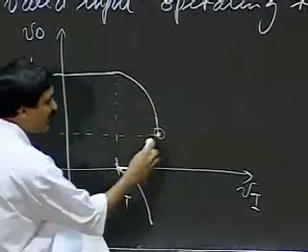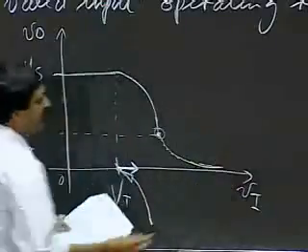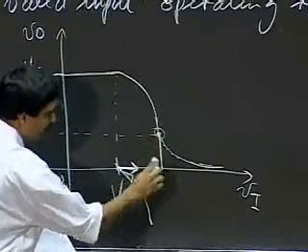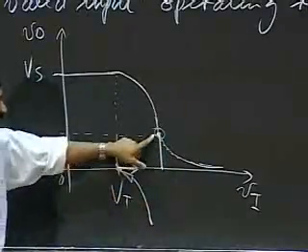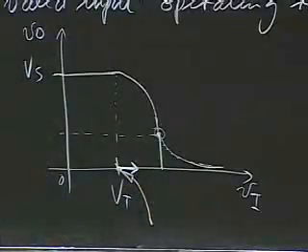So somewhere here, I go into my triode region and begin to show a different behavior than the amplifying square law relationship, and go into my triode behavior. So I need to find out what this point is. Okay, once I find out what that point is, then this will be my valid operating range. So let's figure out what that point is.